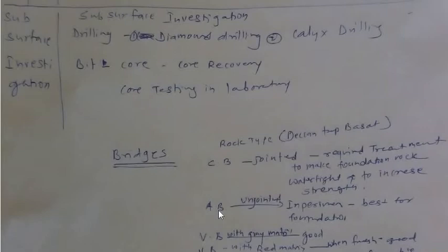Then construct the geological map, select 3 to 4 alignments, construct geological sections, select one which is the best alignment, and then start your drilling program for bridges.